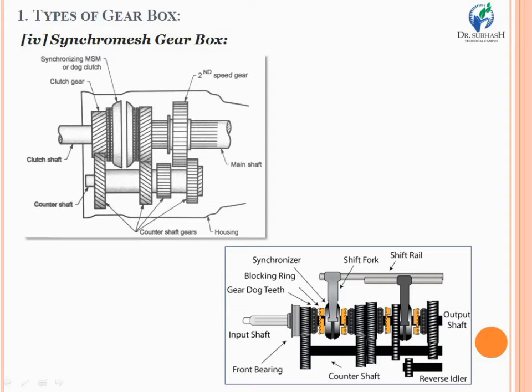Generally, the case cover usually carries the shifting mechanism, and it shields the gearbox against water and dirt. Of course, a shift fork and the shift rail are also contained by the case cover, and it is totally sealed with the housing of the gearbox. In that way it prevents water and other deposits or dirt particles from coming into the housing and causing friction or damage to the teeth of the gears.